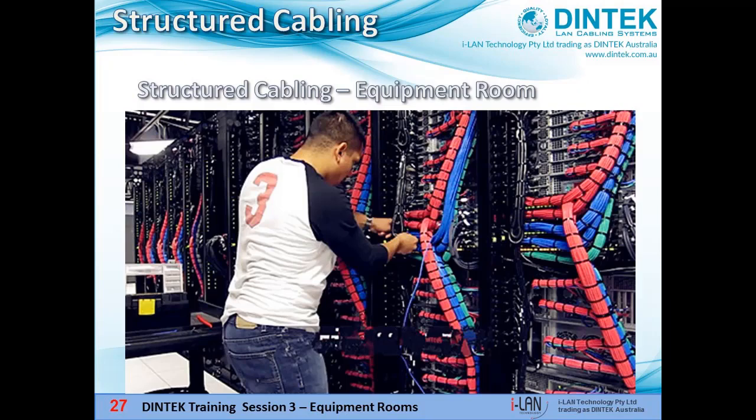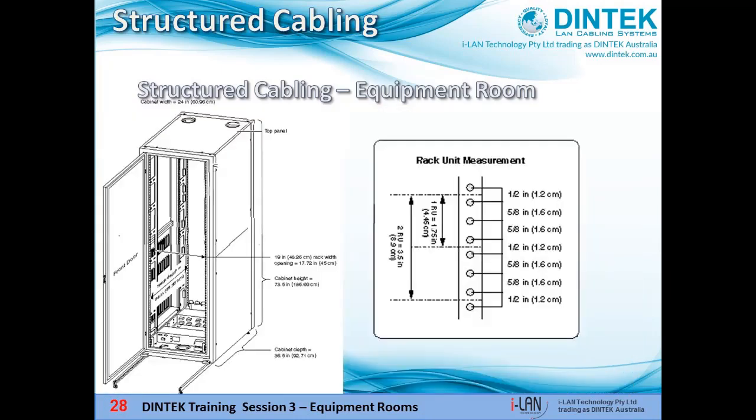There's also evidence to suggest that running cables neatly beside each other can increase EMI and crosstalk, so a dog's breakfast with cables laid randomly all over the place may actually perform better than a neat cabling installation. There's even talk of bringing this into the cabling standards.